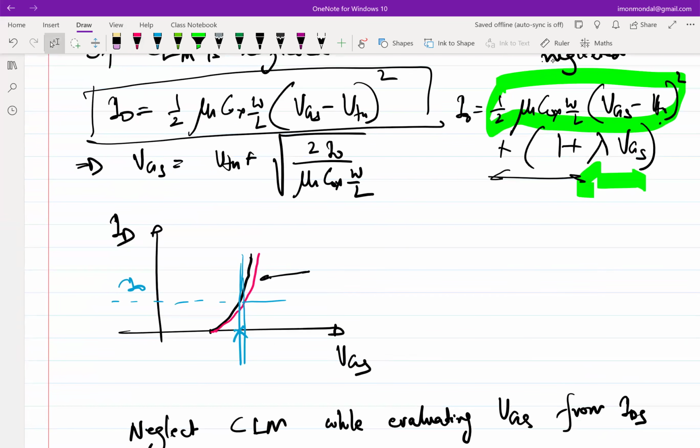Okay, so his question is why the red graph should be on the right. I probably should have explained why I am sketching it like this. This assumes it is not biased with a constant current source, because if it's biased with a constant current source, then the current shouldn't change. So what we are essentially doing is sweeping VGS and finding IDS, right?